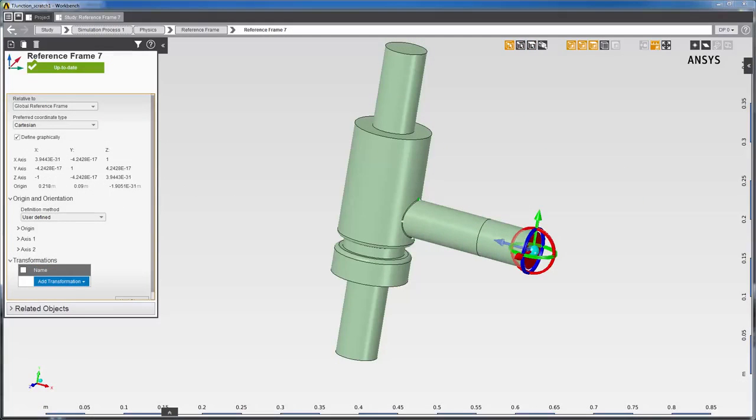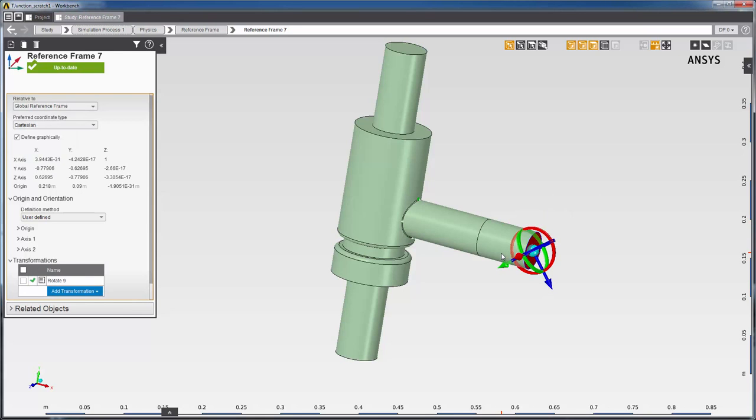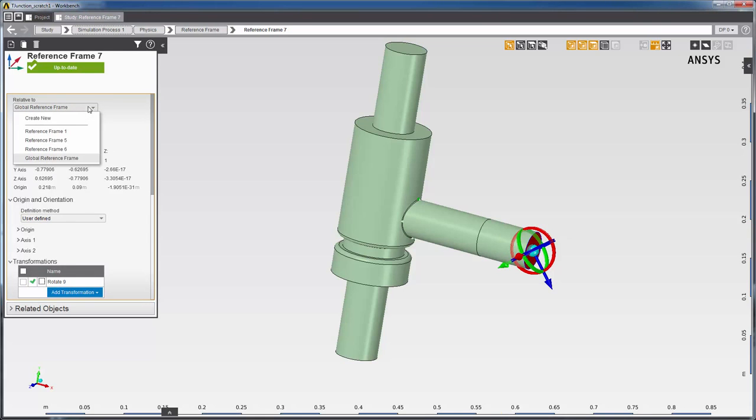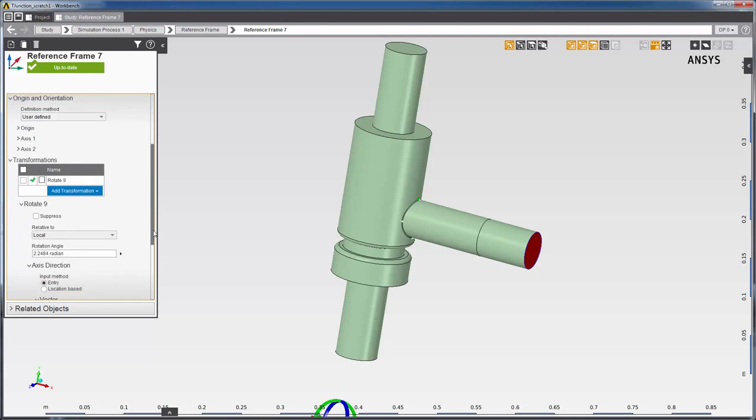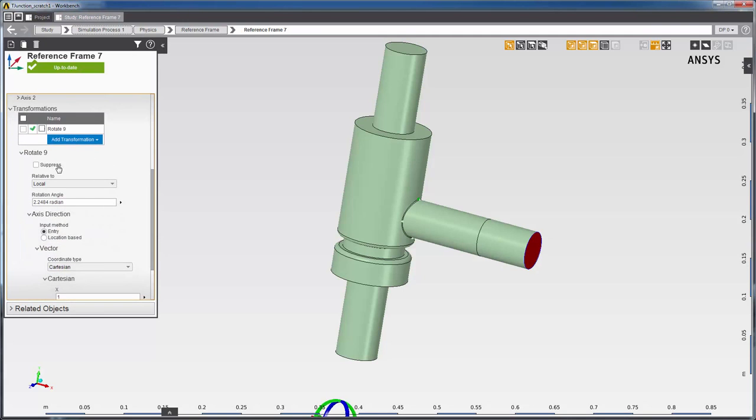We can define these transformations relative to our local axis or the parent frame's axes. The parent frame is the frame relative to which we defined our new frame. Transformations relative to the local axes are done relative to the frame's current position and orientation, like so. If you rotate relative to the parent, the rotation will be about the parent frame's axis. If we had defined our frame relative to a different frame, the transformation would be relative to that one.